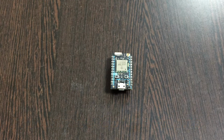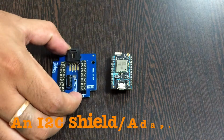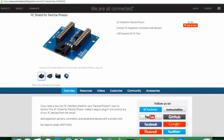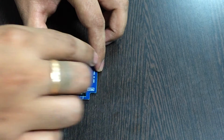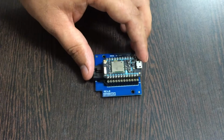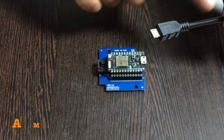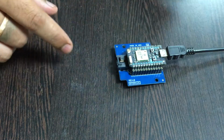Well, coming to the hardware connection setup part, the first thing we require, which you are able to see on my screen, is a Particle Photon. Now this here is an I2C Shield. It's available and can be purchased from the website controleverything.com, and the reason we are using this shield is to make connections easier with other I2C devices. So for that, we gently place this Particle Photon over the I2C Shield and make a connection just like that. Now to power up this Particle Photon, we require a micro USB cable, which you can see on my screen, and gently insert it over this power jack.